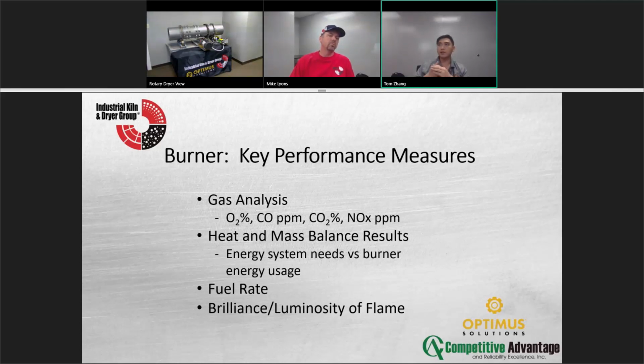In terms of the energy savings, 10 million BTU per hour, is that enough to justify any upgrades or any process changes? Is that a $250,000 savings a year if I just let a pile that's really wet sit outside and dry a little bit longer? This is where we use data, the information from your process, to make business decisions, financial decisions, so that you can work your way from an ROI standpoint. Fuel rate is an easy comparison on energy. And for radiation heat transfer in kilns, the luminosity, the brilliance of the flame, matters. This is where natural gas tends to have a harder heat transfer.